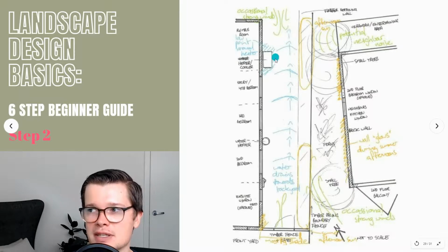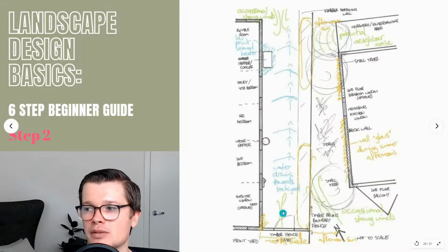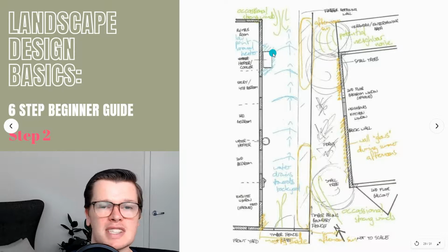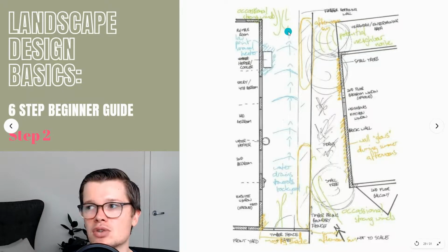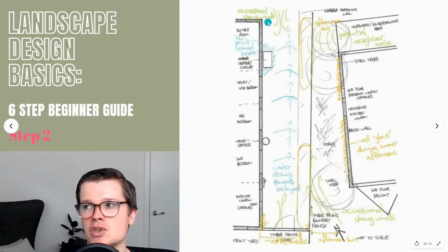The other thing here is there's a low point around the heater, so whatever we were trying to implement, whether we wanted to do something like a French drain down the middle to collect water, you'd have to recognize that you want to make sure you put something here, like a slight slope or barrier, to prevent water pooling in this area, or just another way that you can potentially get a drain in to collect water in this direction. I don't think it's too much of an issue because it's mostly covered by eaves, but it's just something to make a note of.